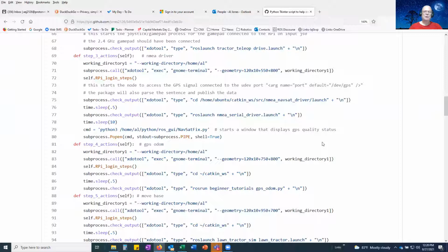But I should go through and update that ROS node that I wrote that takes in random data from whatever sensor and publishes that as an array. And then I said, okay, if you know which field is the heading, I can pull the heading off, and I put that code in to do the unwrapping of the heading so it doesn't bounce between 0 and 360. So I should clean that up so it's a little easier to use, then post that somewhere so that people can use that if they choose to.